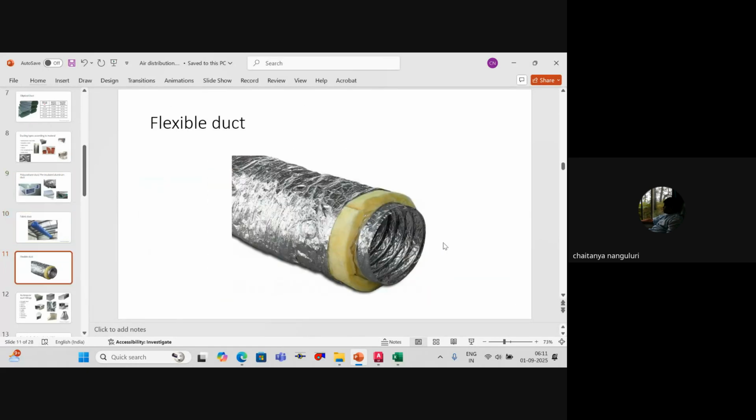So this is your fabric duct. And then we have the last one, that is your flexible duct. This flexible duct, we use in day-to-day projects where, from a rigid duct, we want to connect to an air terminal. See, your design is never constant. What I mean to say is, for example, false ceiling. The architect will provide some false ceiling layout, where exactly your 2 by 2 grid or your gypsum is coming. Can you give a guarantee that exactly at that location installation will also happen?